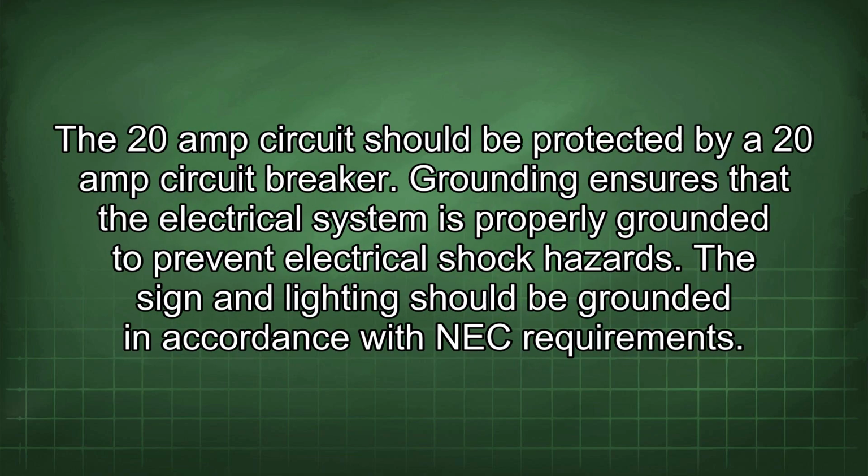The 20 amp circuit should be protected by a 20 amp circuit breaker. Grounding ensures that the electrical system is properly grounded to prevent electrical shock hazards. The sign and lighting should be grounded in accordance with NEC requirements.